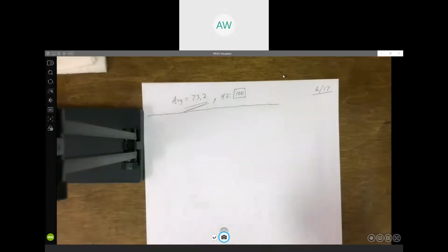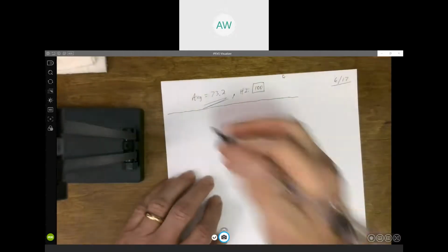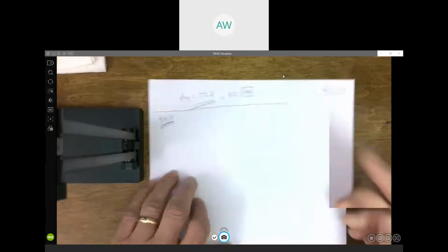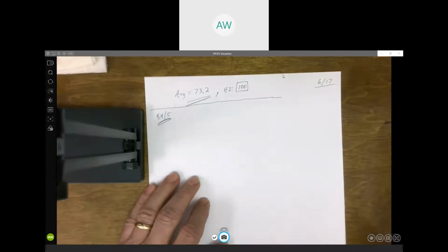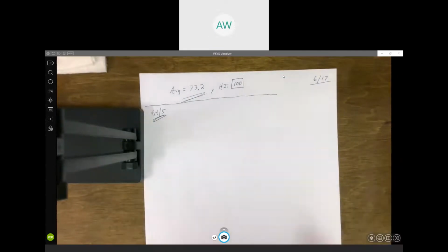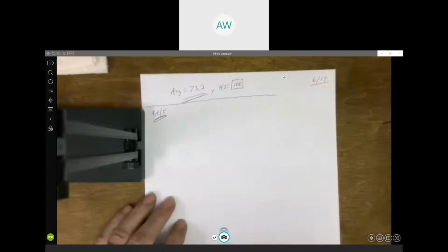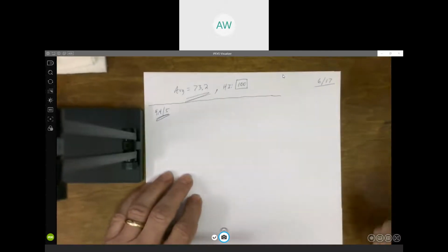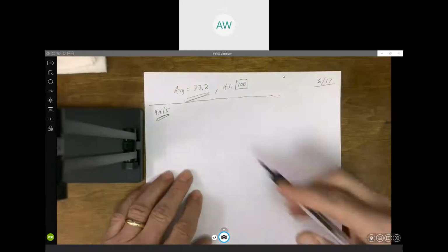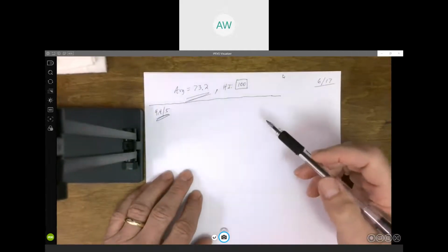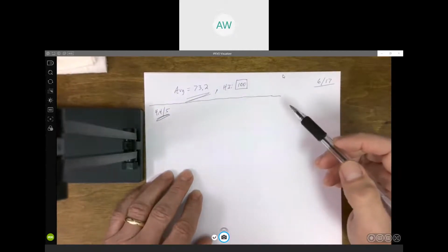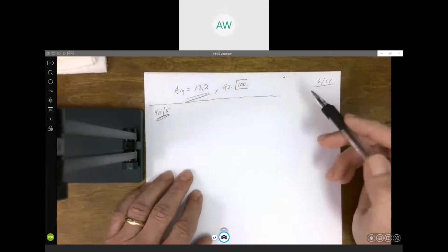All right, so now back to this, which was in your textbook, sections 4.4 and 4.5. Again, we're talking about statically indeterminate structures. These are structures that we cannot solve just using statics, and by that I mean our three equilibrium equations. In order to solve these, it's going to take a combination of our equilibrium equations as well as what we know about deformation. So we're basically going to couple two things that we already know.